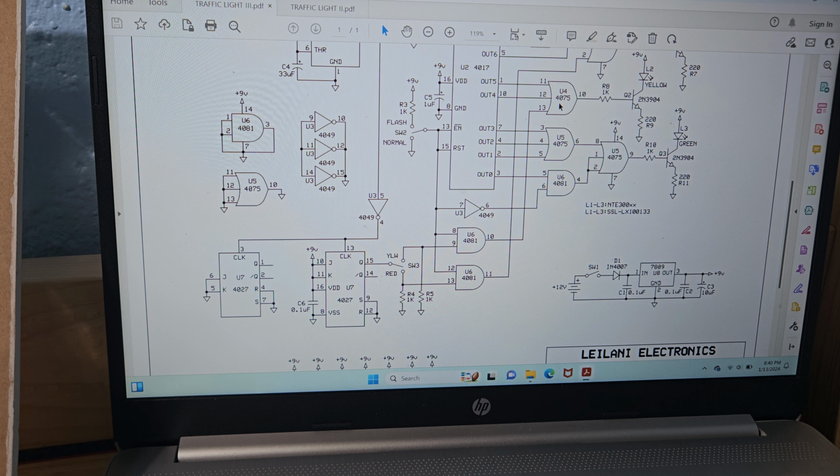And remember, this is the OR gate. So anytime they see a high, it's going to give you a high output. So it'll flash yellow and it'll keep doing that forever and ever. And then if you want to toggle it red, now your clock pulse goes down to the AND gate for the red. And now it toggles that. And that's how you can toggle between your red flasher or your yellow flasher.